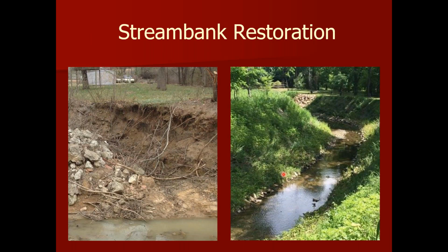environments. Stream bank restoration, a lot of areas, this is on a channel bend, as you can see the sloughing at the toe, rock was put in to try to stabilize that. Could talk a long time about rock, the pros and cons of different types of rock sizing equations, but the point would be to try to put nature back into the equation and put a system in place that was able to hold a slope behind it.